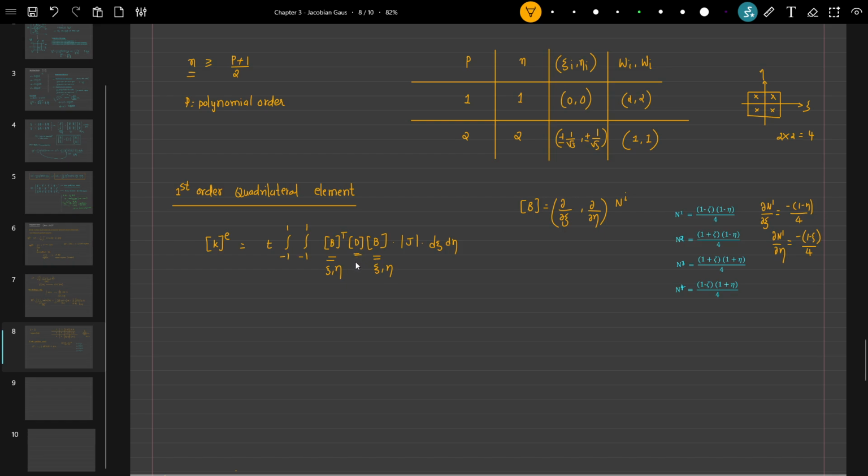That is a sigma epsilon relationship. But when we multiply these matrices, the polynomial order will be of zeta, eta, zeta square, eta square, zeta eta. So after multiplication of matrices, these could be the terms. So the maximum polynomial order is 2. So P is equal to 2 for our first order quadrilateral element.